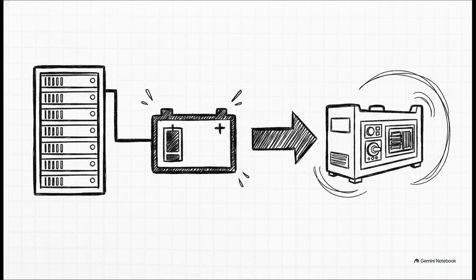Well, it all comes down to the discharge rate. By consolidating workloads and literally slashing the continuous wattage draw on the floor in half, you effectively lower the battery discharge rate. This instantly doubles your UPS backup runtime. It stops the rapid degradation of those batteries and buys the diesel generators plenty of time to spool up and stabilize the load safely without dropping any critical banking systems.